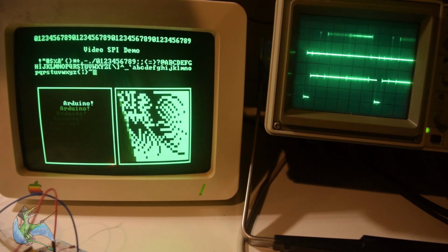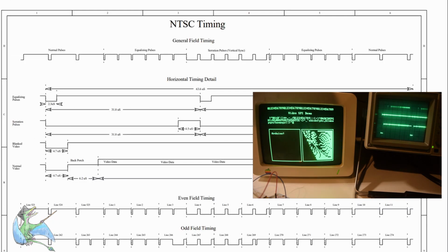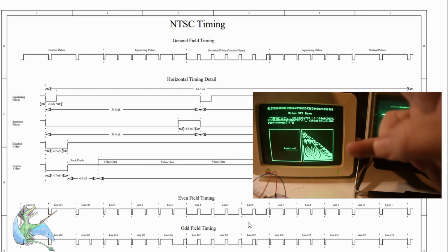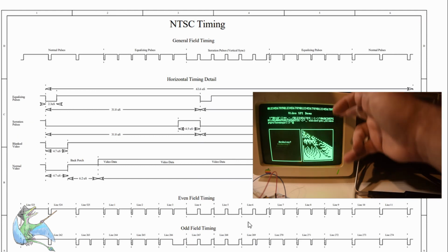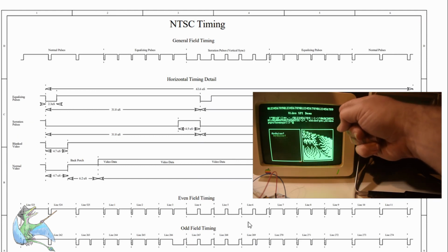Now if we look over at the screen here, technically, details like the vertical sync period are more complicated than that. If you're doing broadcast quality NTSC, which we are not doing, you have to worry about interlacing, in which case basically every frame is actually 2 fields which are slightly offset from each other.